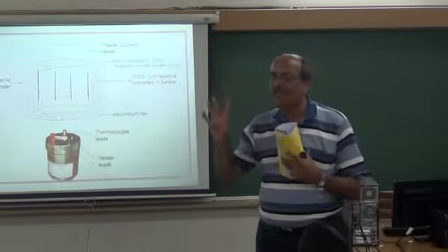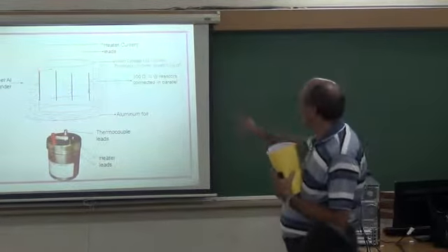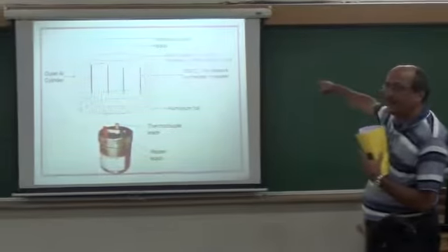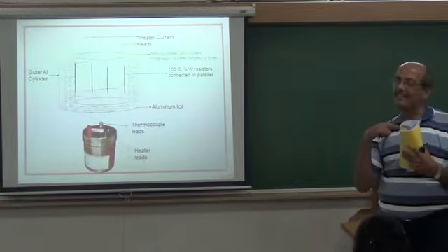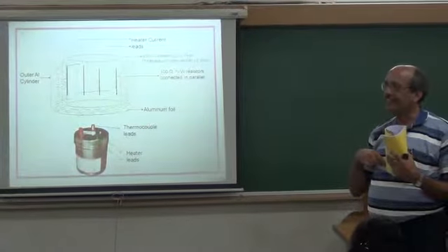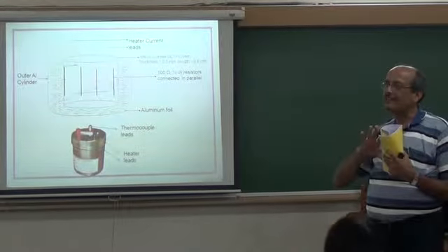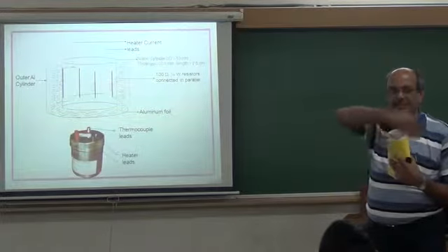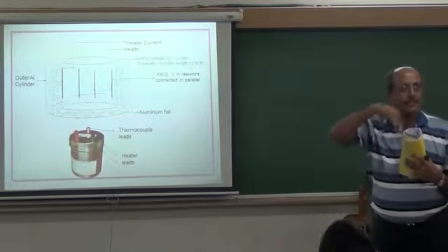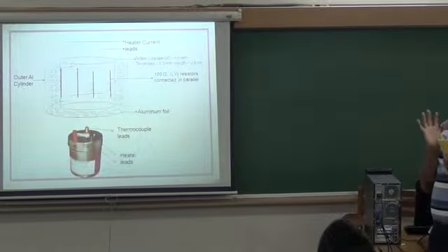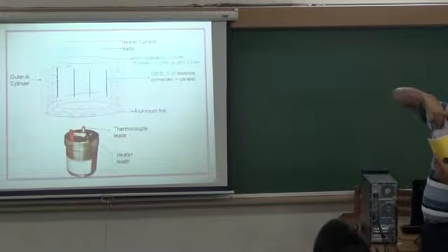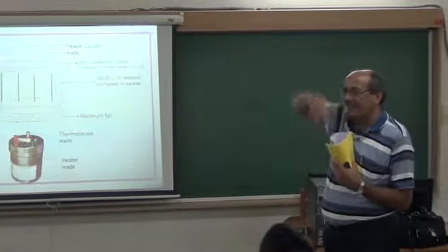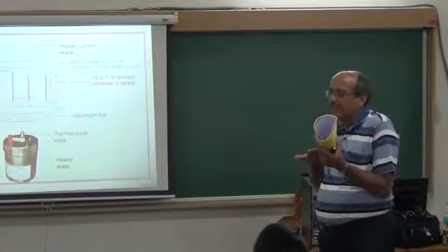Now you take 5 resistors of 100 ohm, quarter watt. One end is inserted here, the other end is inserted here. So we have one resistor here, another resistor here. So we have 5 resistors equidistant lying onto the surface of the Teflon cylinder. Now the inner wires that are connected, we twist them together, and the lower ones are also twisted together.